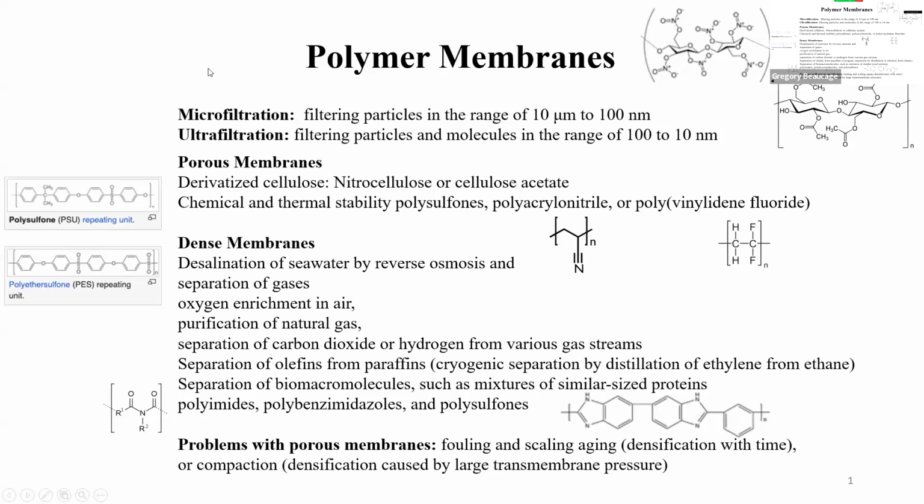Anyway, they make all different kinds of membranes, right? If you want to do microfiltration on that scale, you can do it just by using a non-woven polypropylene. You can just spin polypropylene fibers, extrude it, then blast it out onto a conveyor belt that's flying by and let it raster all over the place and end up with a dense mat of polypropylene fiber. And it can make pores on that size scale. So that's the cheapest way you could possibly do it.